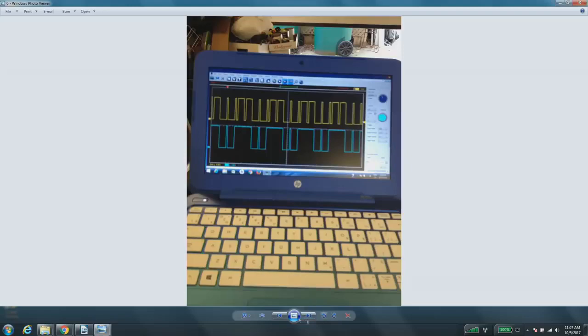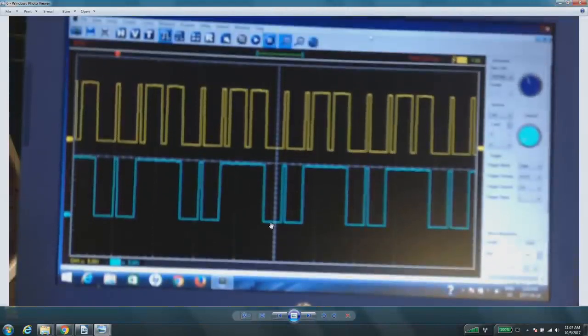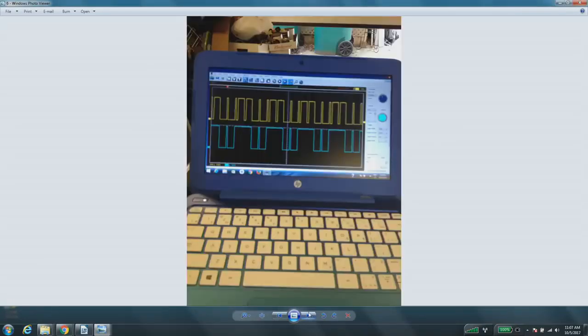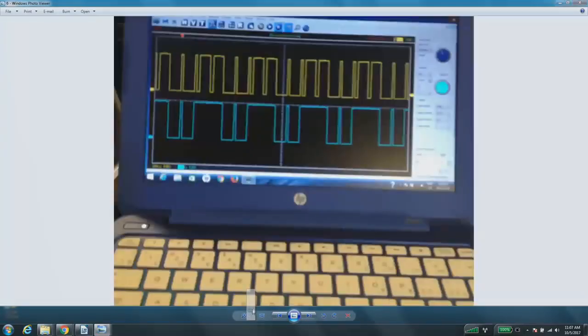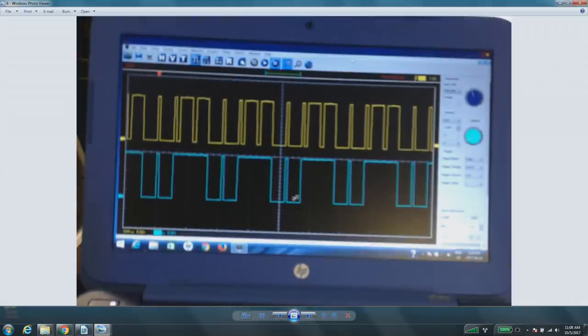This is the pattern that Mike sent me for us to take a peek at. Ooh, we'll zoom it in here. And as you can see, yellow is going to be our bank 1, blue is going to be our bank 2. Yellow pretty much looks like what we saw on our known good, right? We got short, short, long, long, and if we go back here, we have short, short, long, long. So this is one camshaft revolution, another camshaft revolution, and our blue trace here, this is our problem child right here, right? We got a short pattern, but we're missing the rest.